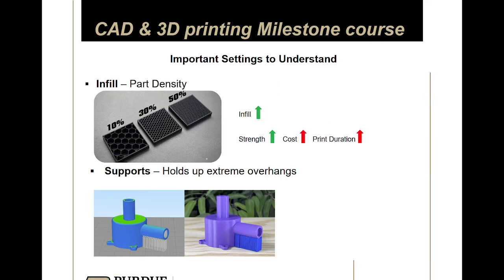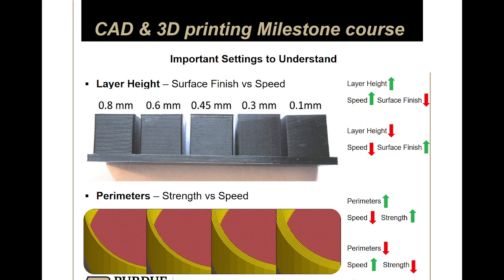Okay, well, the next slide's about infill, but most 3D printed parts are hollow. So controlling the outside thickness is a very important parameter to keep in mind when you're making parts. Because if you have a very thin outer section and you want it to be strong, it'll probably break. So typically I change the number of perimeters if I want more strength before I change infill. I'll talk about infill in a second. It's measured in either the dimension or the number of perimeters. I would say the standard perimeter count is usually around 3 or 4.